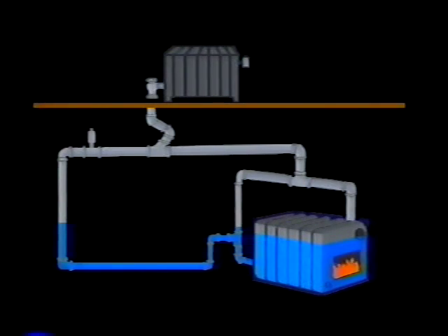The burner ignites. Water in the section waterways is heated, producing steam. The steam travels up through the water and collects in the steam chest, travels through the upper port openings to the supply riser, into the system header, and on into the supply main.